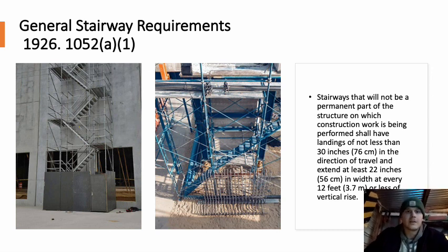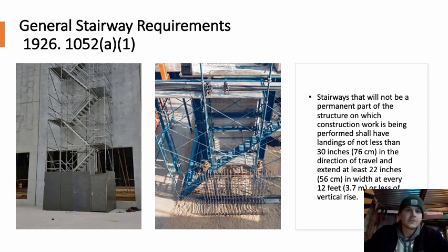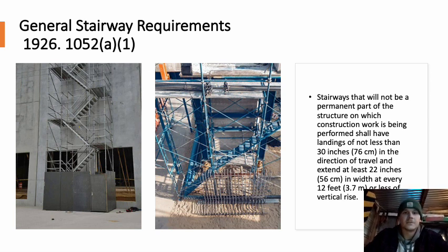We like that. And then on the right, it's got a couple things going on. First, it has one stair going up, and it's obviously over 12 feet in length, so it needs a landing. So that's not correct. Another thing, which we'll talk about next, is guardrails and top rails, and it doesn't have those either. So we don't like to see that one on the right.